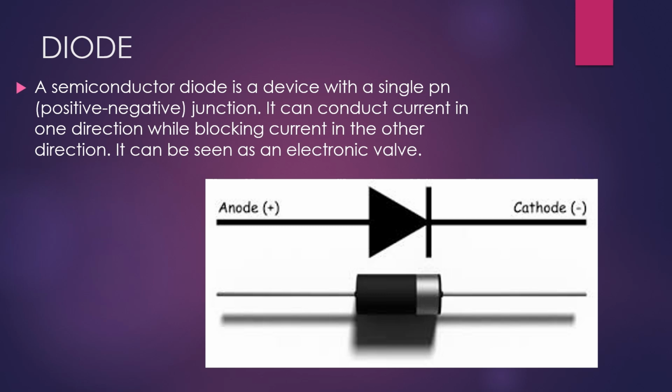And in the next slides we'll see how we actually measure a diode, how we forward bias a diode, and how we reverse bias a diode, as well as how in the multimeter we can actually get the value we want for our diode. In fact, the standard value for the diode where you have to measure your diode is between 0.6 volts and 0.7 volts.